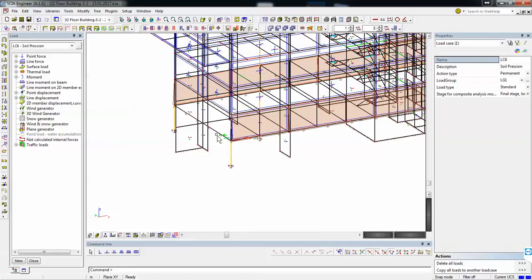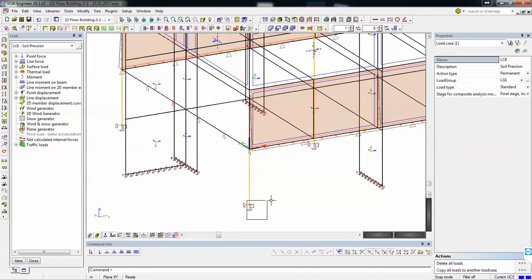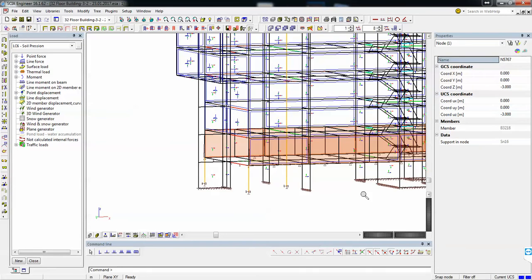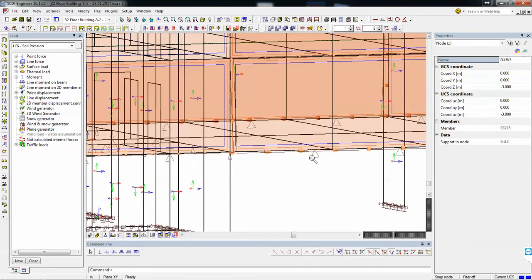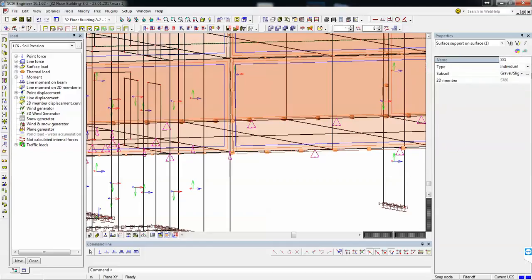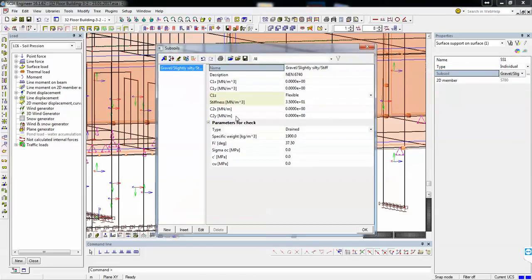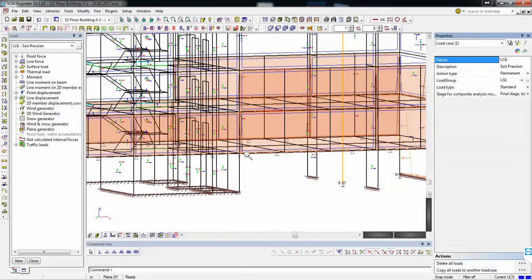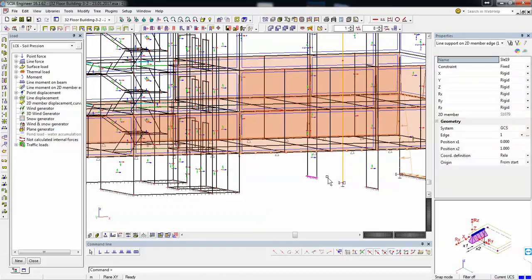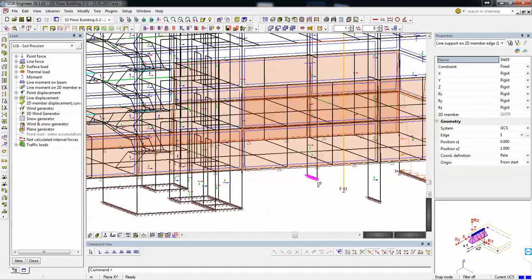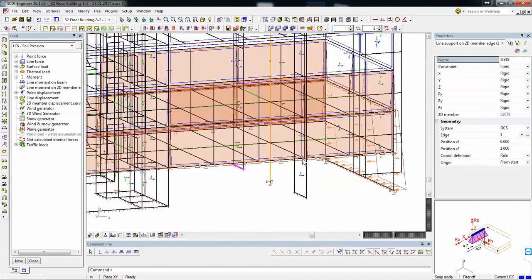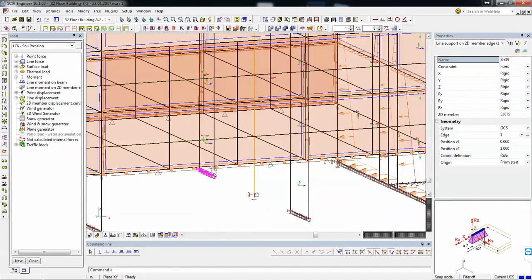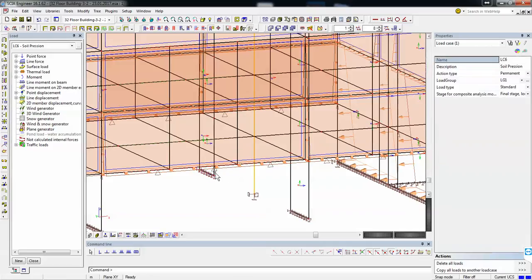Okay, and also you lowered all vertical elements lower than this slab, and this slab you said it's gravel. Okay, it can be one approach like this, but this is not a mat foundation by any means. So this is the way you drew. You will have local elements on soil or on rock, and then this is only a slab that sits on the ground, so that's all. This is not the foundation.